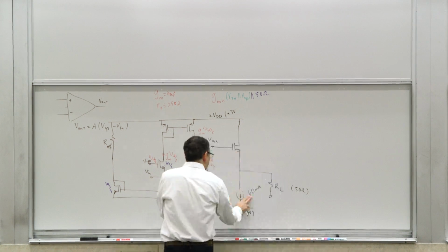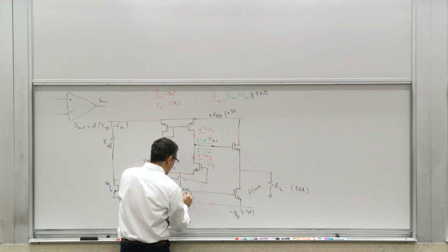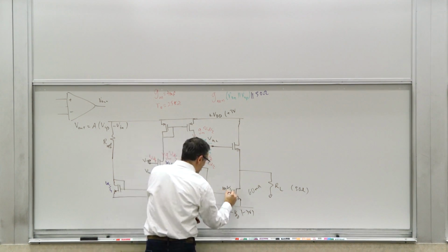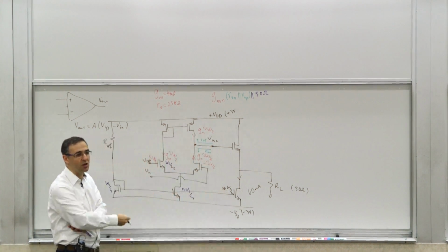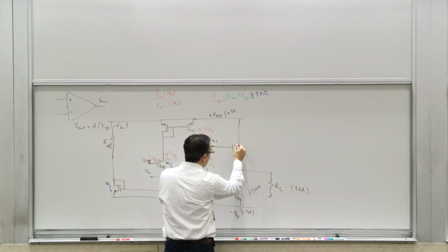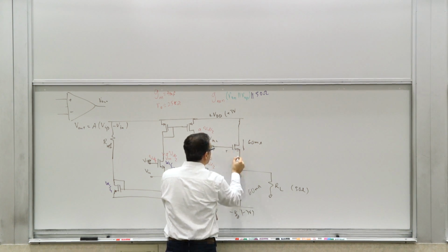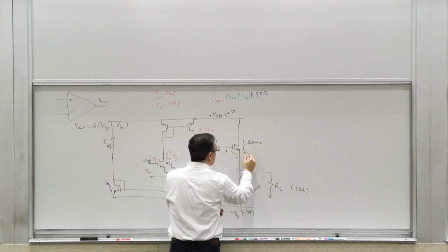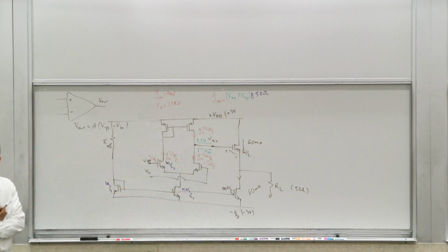How do I make this 60 milliamps? Well, we put a transistor here that nominally for the M times W1 L1 can draw 60 milliamps off of that. So that may be a large scaling here, but that's fine. And then you have to make sure that this guy can draw this kind of current without dropping a significant amount of delta VGS, which means that probably it should have a reasonably large W over L. Again, qualitatively, right? So that's where you start off with something like that.